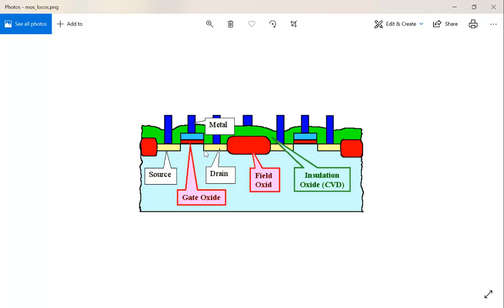So the way they made it is, at the very beginning, the field oxide, the fox here, is just everywhere, one homogeneous layer on the surface of the silicon substrate. Okay, and when your design file defines a transistor in a specific location, it opens up the fox layer. Remember how to open it up? How can I open up the layer on the wafer? Photolithography, yeah. It might be a very complicated process, but you can imagine how that works.